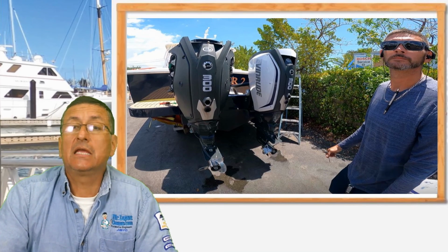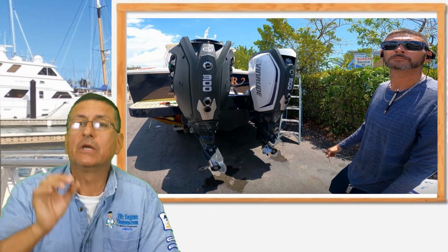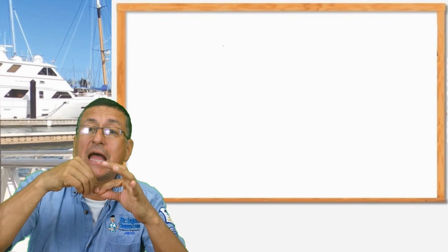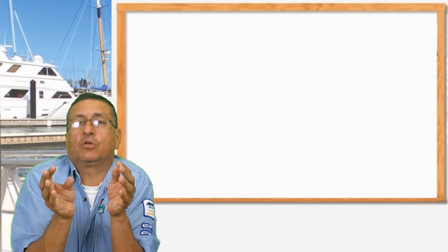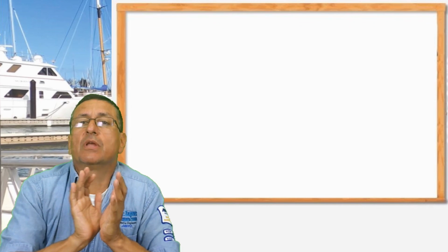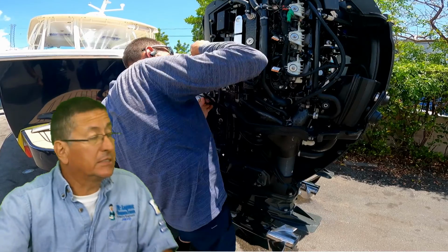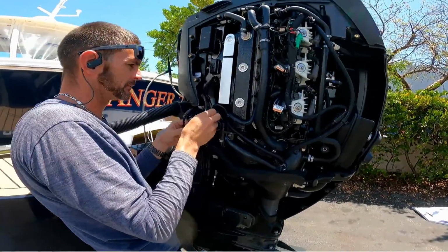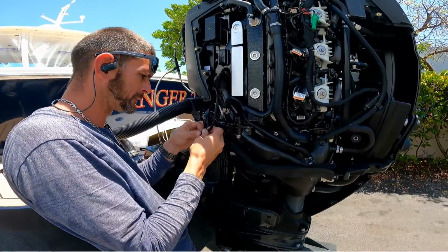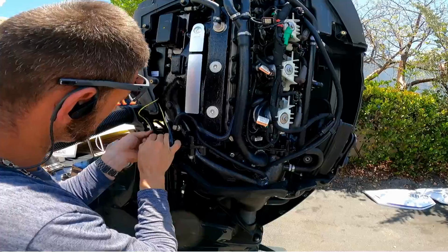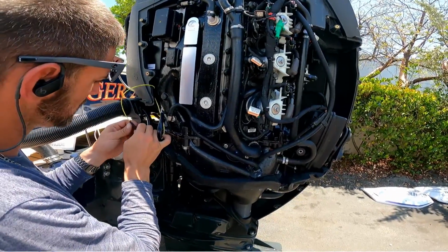And now Danny starts to check cable by cable, sensor by sensor, to see if the cables are in good condition: no cracks, no bends, no burns, because in outboards all the cables are enclosed together and pretty close to the block of the engine. In this particular case, that was the process, cable by cable. It's a long process, in this case more than 2 hours. Danny is checking the condition of the harness, verifying the ground, that the wires are not loose and in good condition, and that the connection is tight.